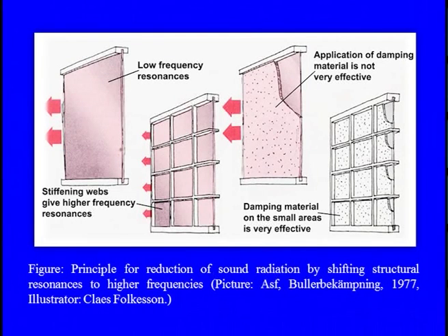But if you keep the damping material all across the dimension of this wall, as in the third figure, even after keeping the damping material, since the frequency is quite low because of the dimension, we cannot effectively control this. This is one of the beauties of vibration theory.